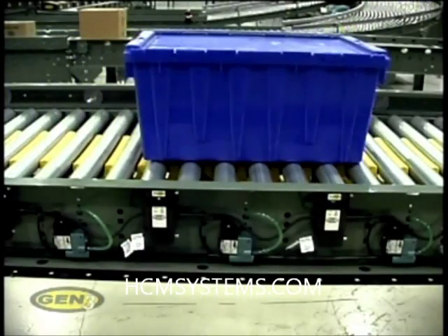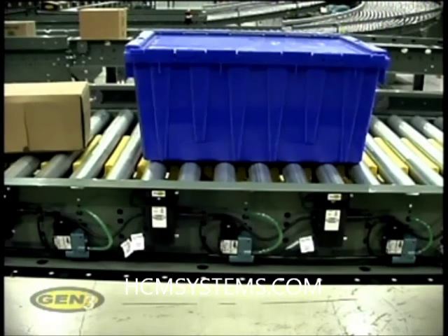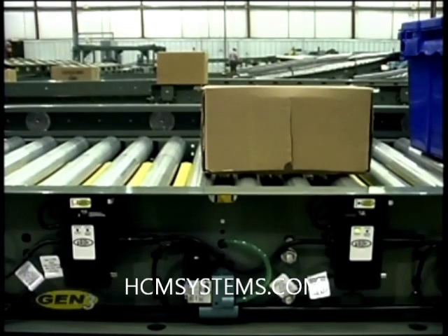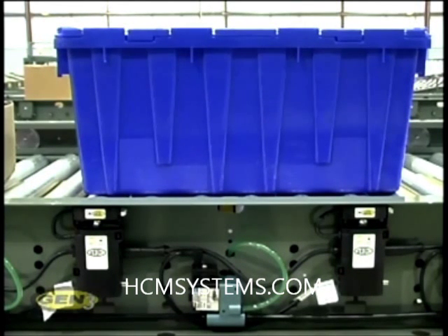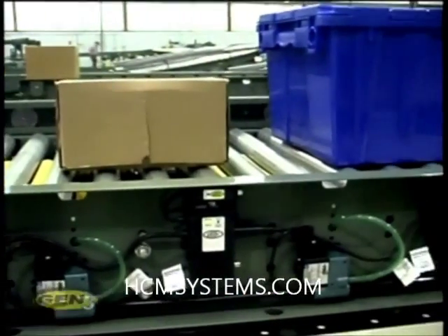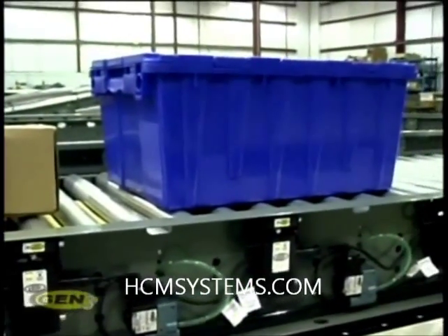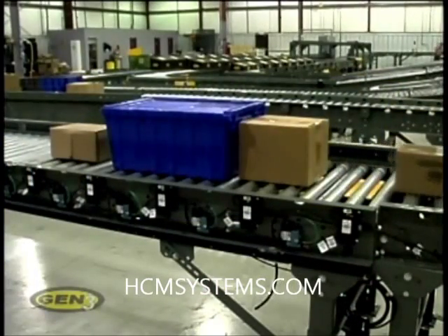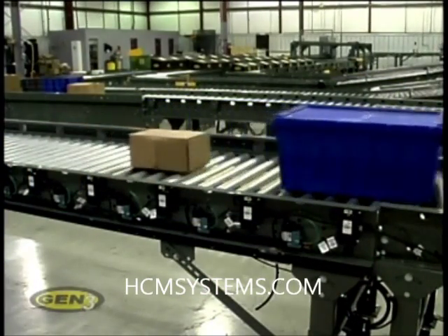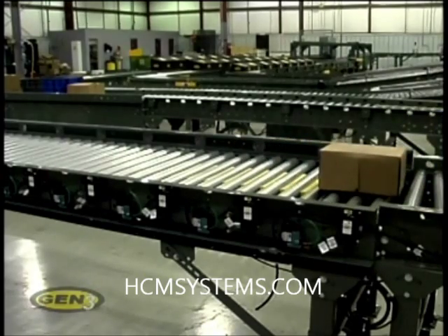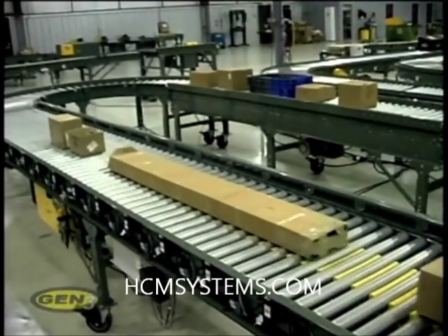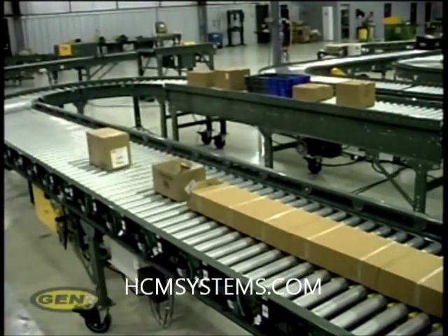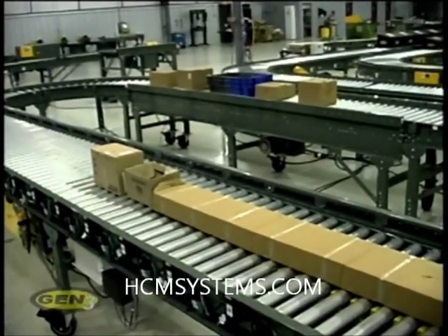For example, if the conveyor is built up using 12-inch base zones, a 9-inch box will be assigned one base zone, while a 21-inch box will be assigned two base zones, or 24 inches. The cartons are thus allocated the proper number of base zones as required by the cartons. As cartons are transported or released, a gap equal to one base zone is created between cartons, regardless of the carton length.